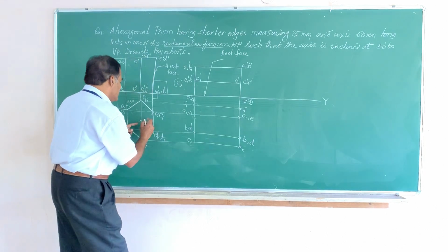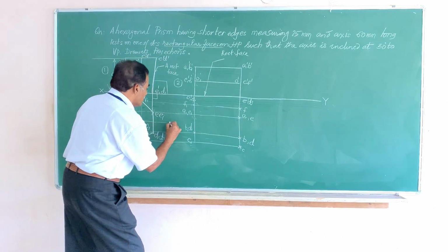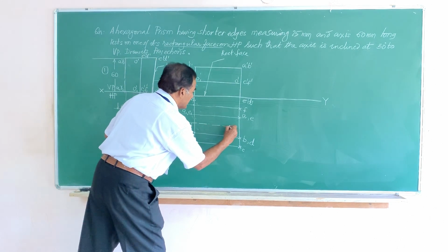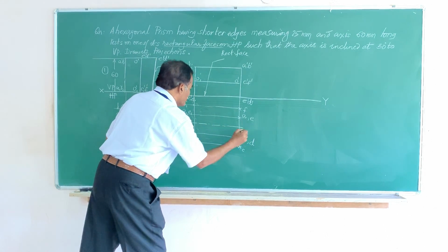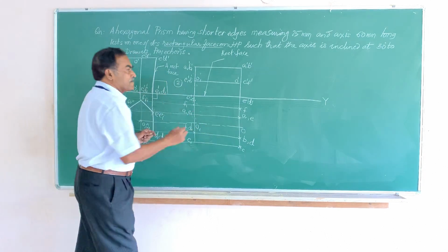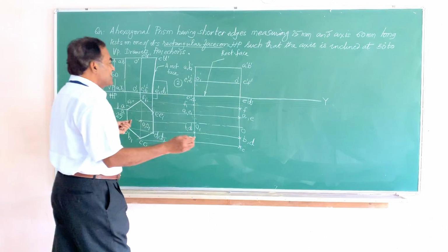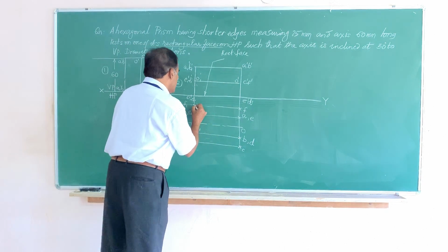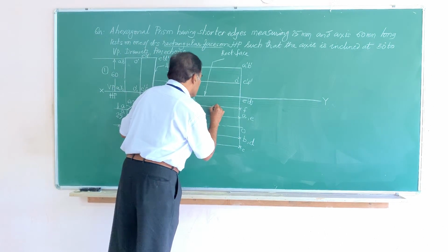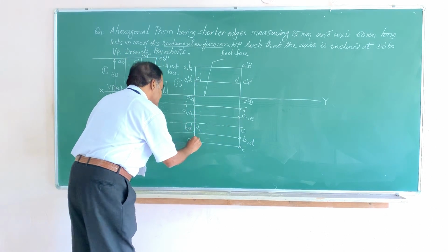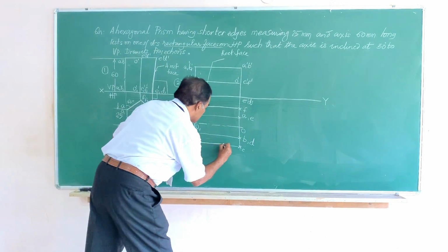So the axis is here. It is very essential to locate the axis every time. So dash dot, a line like this. This is going to be your O and this is O1. So as per the rule, after getting all this, you have to join all these lines by visible lines. So all these border lines are visible. Hence I represent the top view like this.